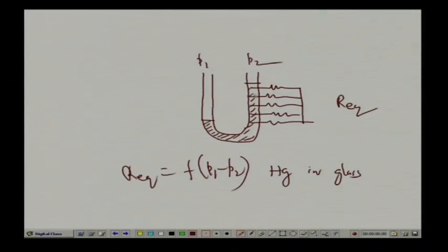But as you know, this is a discrete form. So, suppose in between the two resistances a liquid column comes in, it will not get any change until the manometer liquid touches this resistance and gives a change in resistance, right. So, these are all about manometers. Let us go back to the other types of gauges.